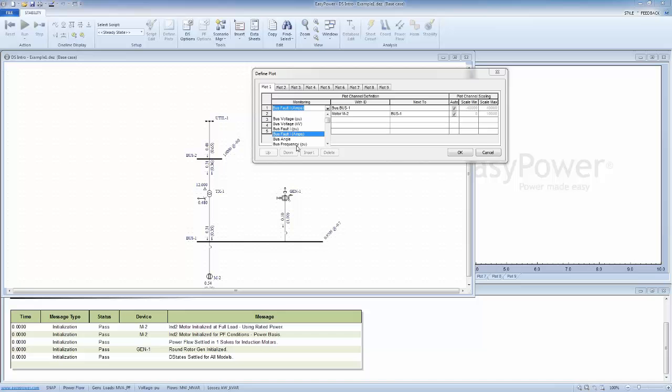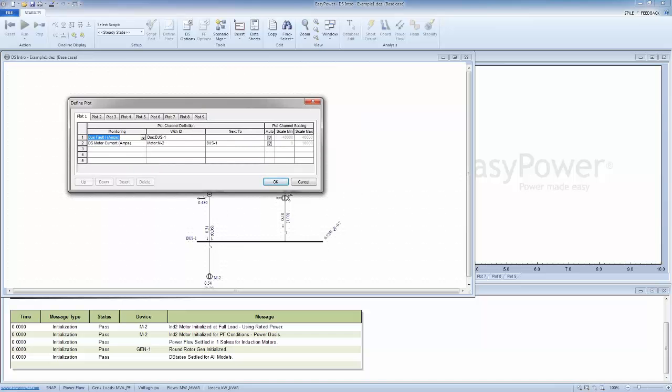So if the frequency goes up by, let's say, 30%, the value of X is going to go up by 30%. And we don't cover it in load flow. We don't cover it in short circuit. Naturally, no other software package does it in a normal short circuit, and I don't want to talk about other packages in the market. Let me limit it to a general statement that load flow algorithms were never designed to consider frequency. So the point is that the frequency is modeled in the system, and you can go and see how it changes.